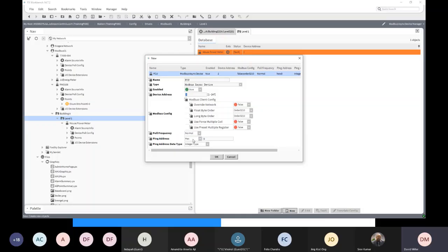So you can say, starting at register 5, I want to read 10 registers starting at address 5. That Modbus message will get sent to the slave device. The slave device will reply back with the contents of those 10 registers, starting at address number 5.